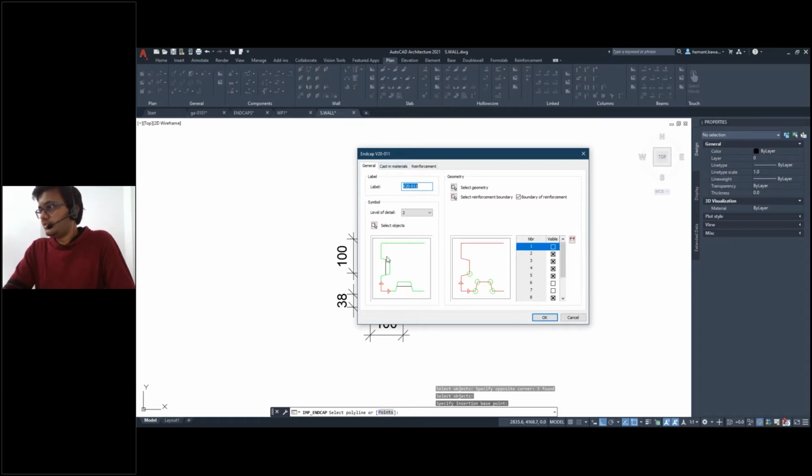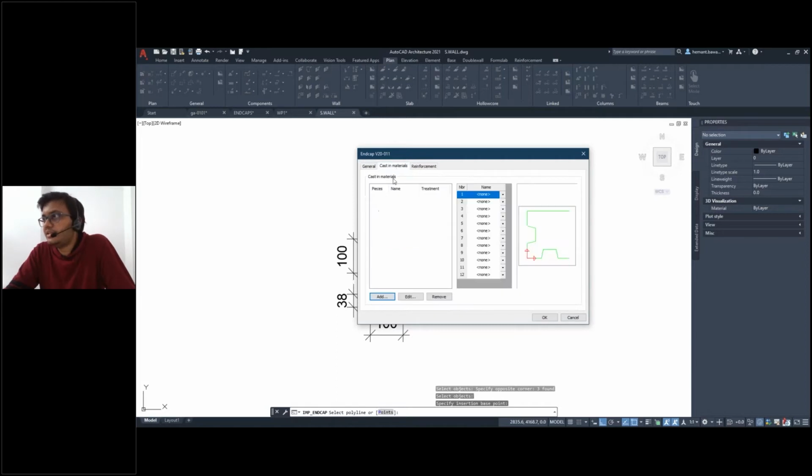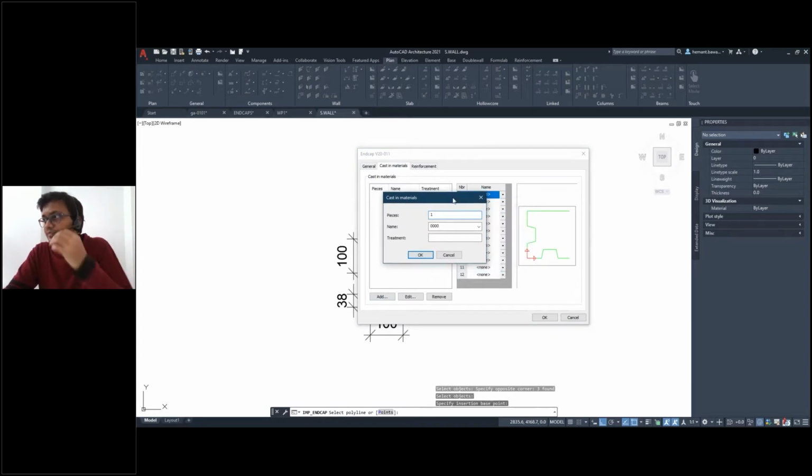Now we also have, as you can see, some line here. If we need to produce some conduit or maybe an electrical duct along with these end caps, we can add this into the custom material. We'll be scheduling this in the shop drawing, and it will be scheduled according to the length of those recesses or the ducts.